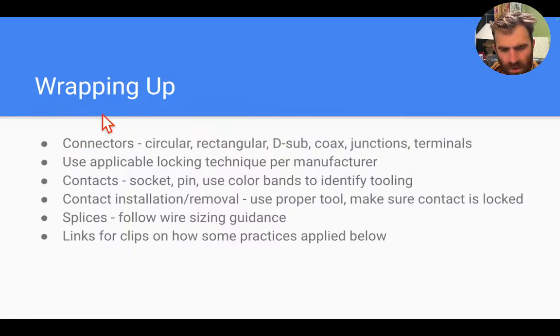Whether that's a ratcheting or bayonet type, or a screw type, if there's a witness marking on the connector, you want to make sure that that's covered up so that everything is secured. We talked about the red band that goes around the circular connectors, or coloring that would be on the bayonet studs of a connector as a way to see whether it's secured.